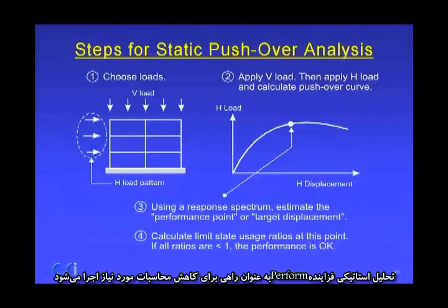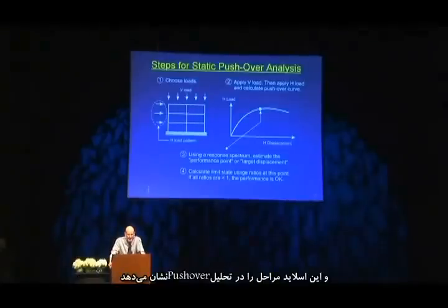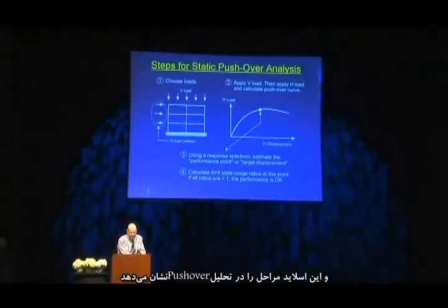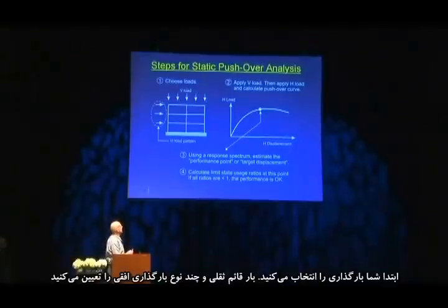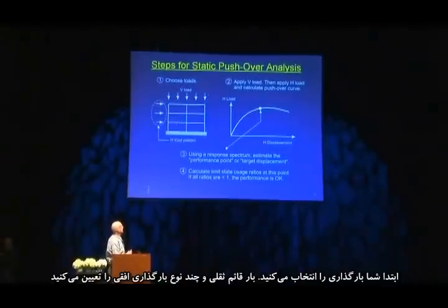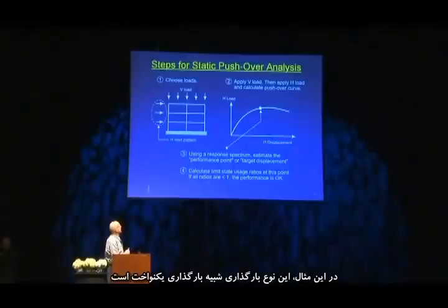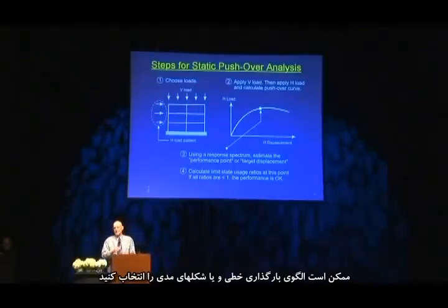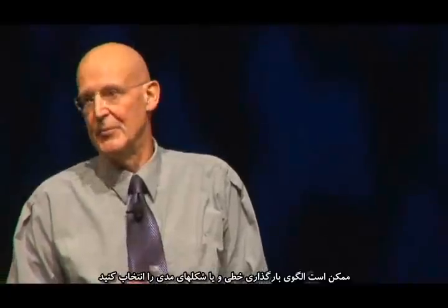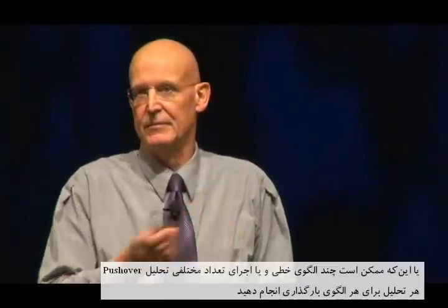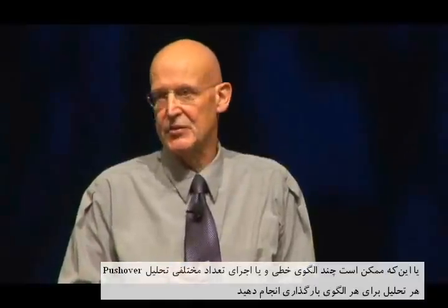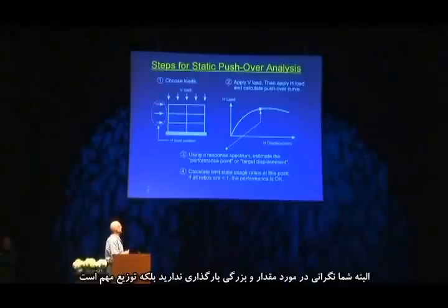reduce the amount of computation, basically. And this slide indicates the steps in pushover analysis. Firstly, you choose the load. You specify the gravity load vertically, and some horizontal load pattern. In this case, it looks almost like a uniform load pattern. You might be linear, or you might base the load pattern on the mode shape, or you typically would have several load patterns and run a number of different pushover analyses, one for each load pattern. But you don't worry about the magnitude of this at this stage, just the distribution.